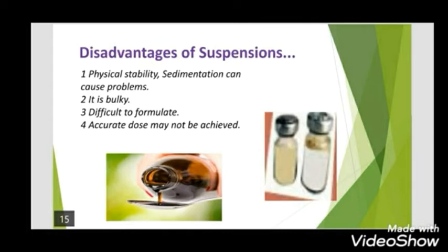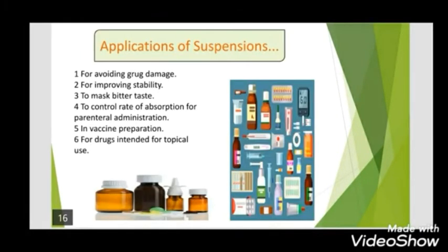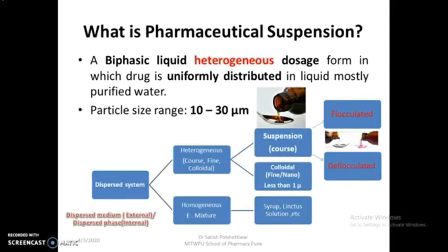An agent for thinning the suspension of slurries. They are low molecular weight anionic polymers, and the examples of deflocculating agents are polyphosphates, lignosulfonates and water soluble synthetic polymers.